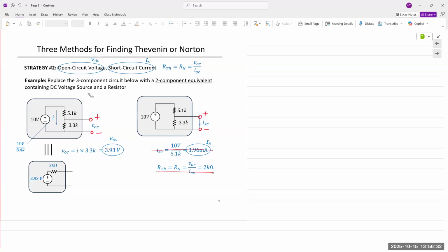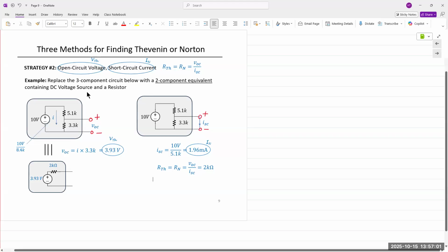Just understand the concept. You have a large circuit and you're trying to determine the Thevenin equivalent network between any two pairs of terminals. In case of the voltage sources, we simply use the outer terminals of those batteries, right? But regardless, it is a linear circuit and you have only two terminals at the output. So you're trying to measure the Thevenin voltage, the Norton current, and the Thevenin resistance, all from those two terminals. And to do that, you apply a variety of techniques.